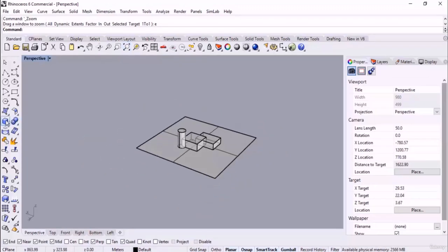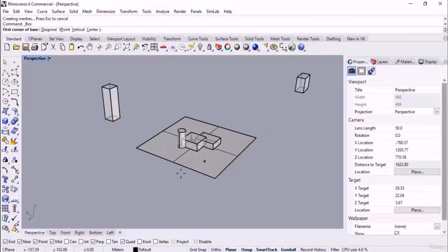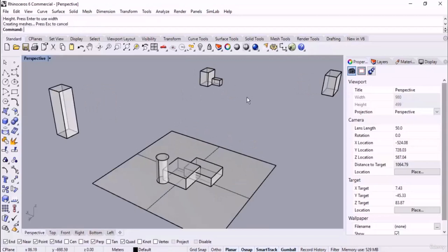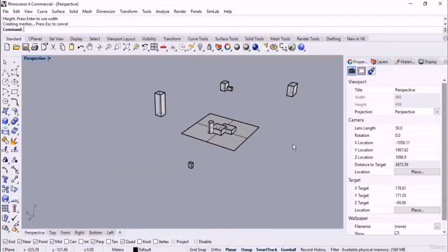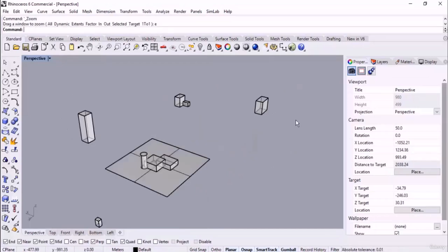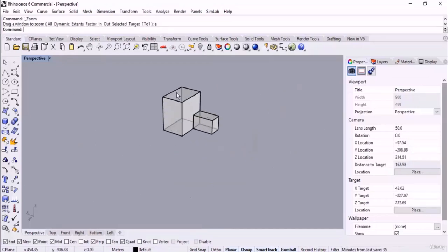But what about zoom selected, which is very useful and has many functions. I place some objects this way. I just want to tell you the example. Suppose that I want to work on each of these new objects in the scene, zoom extend is no more practical here and it is not functional, so I type Z enter, E enter.